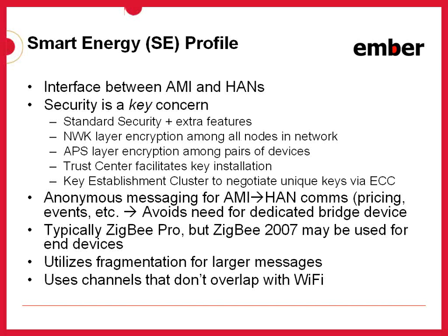In regards to ZigBee versus the ZigBee Pro feature set, smart energy networks are typically ZigBee Pro because they don't have the kinds of backwards compatibility features with the ZigBee 2006 feature set, but you can use the ZigBee 2007 devices for the end devices. We'll talk about the node types in a different presentation.